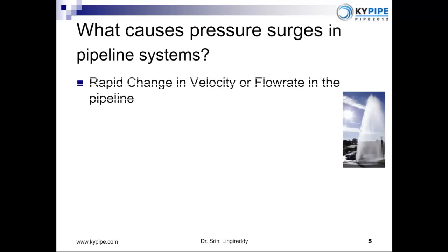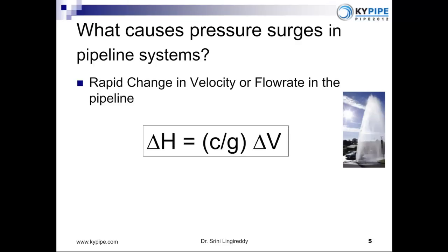Now, check valves are required to protect the pump stations, but because of this reason, there have been many incidents in the past that can be directly attributed to the check valve, where the rapid changes in the velocities have created a rapid increase or decrease in the pressures and the consequent damage to the pump station. The manufacturers are continuously trying to improve on their designs such that the change in velocity would be minimal, while the check valves are trying to prevent the reverse flow.